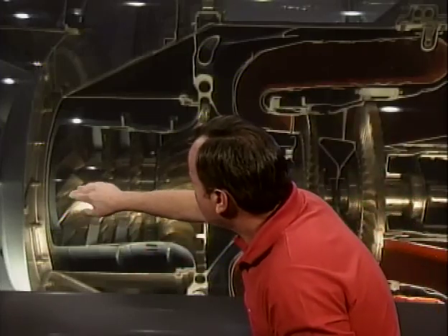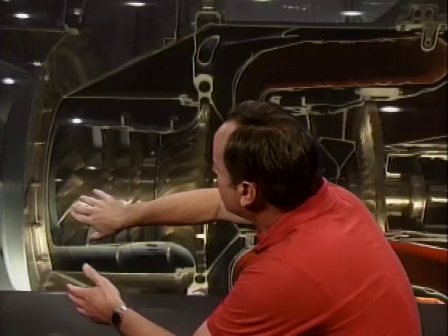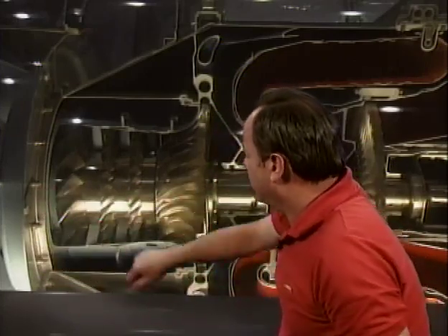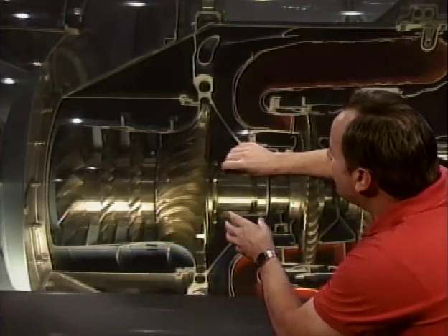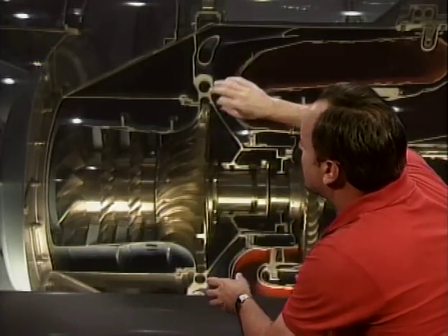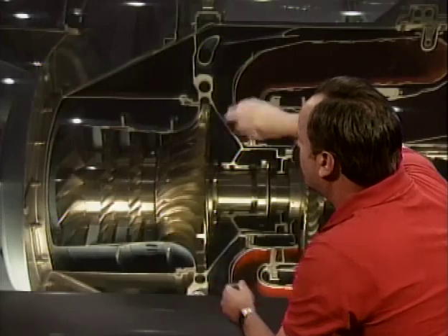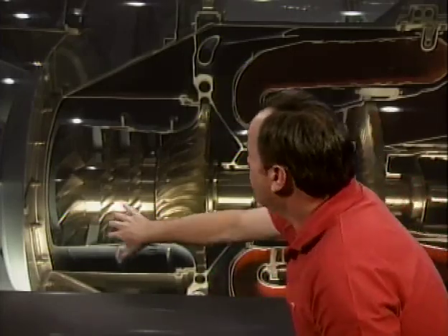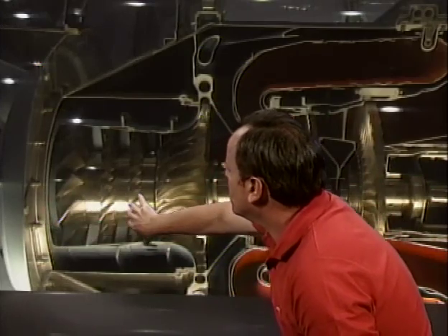And you can do that by managing the angle of attack of these individual blades. Well, one way you do it is make your power changes smooth without having rapid RPM changes. And the other thing you can do is adjust the air coming into the engine so that you don't have big angles of attack. Or you can actually relieve the load on the compressor by bleeding some air off during low thrust and low RPM conditions. So let's assume that you want to keep this air flowing smoothly in the compressor.